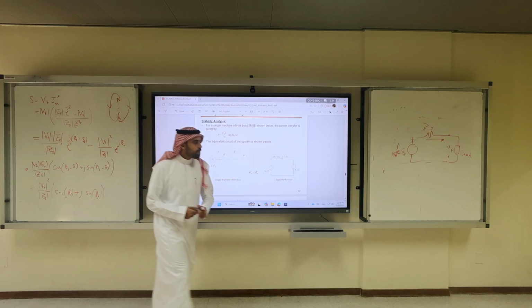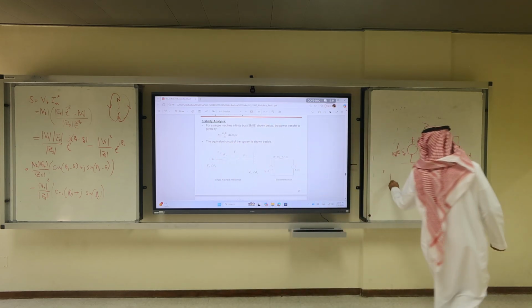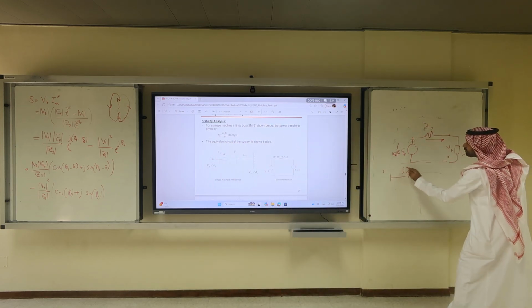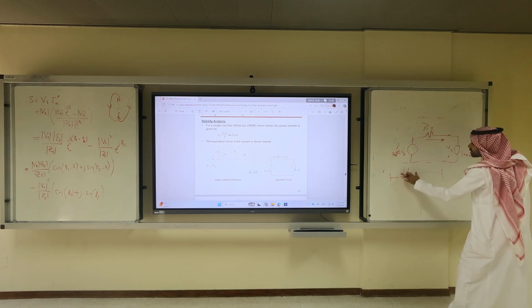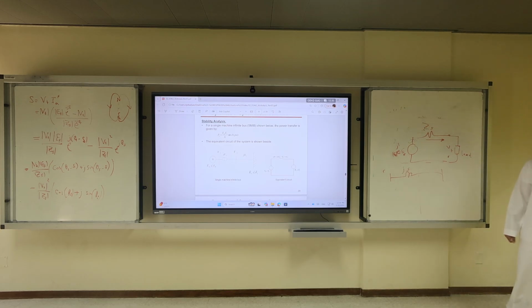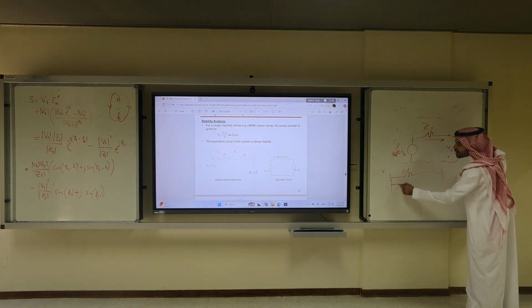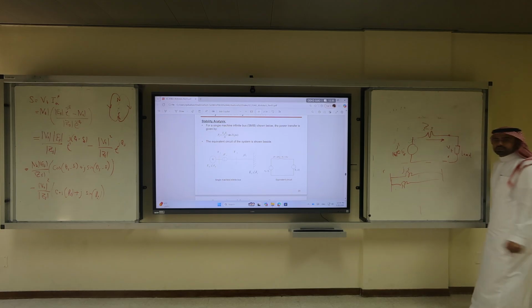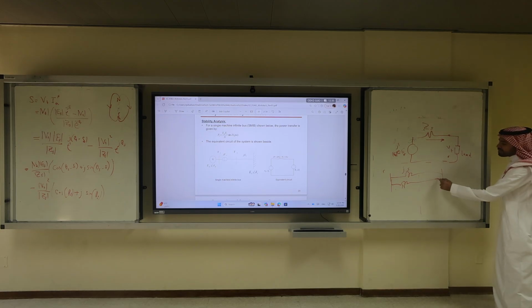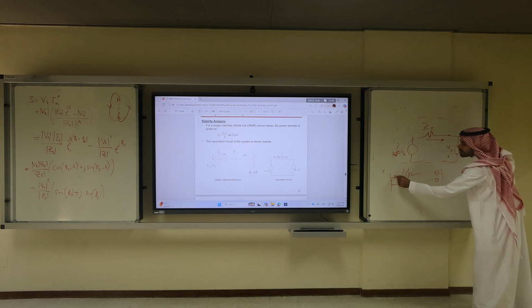Let me give you an example. If you have a line of impedance J5, can I make this impedance 2.5? Yes. Just add a parallel line. J5 parallel J5, that's the equivalent J2.5. And easily you can have it by having a breaker. You usually have breakers.